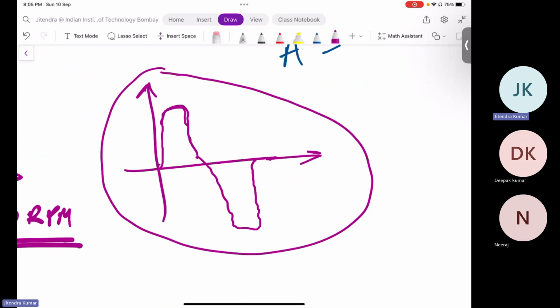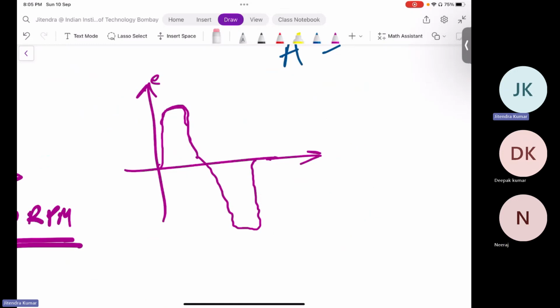Okay, so this EMF you recognize, right? This EMF from the DC machine you recognize. Now, to produce torque, you just have to provide a current pulse wherever EMF is maximum, such that E and IA will generate the power or torque. To give such current pulses, you will require certain power electronics converters.